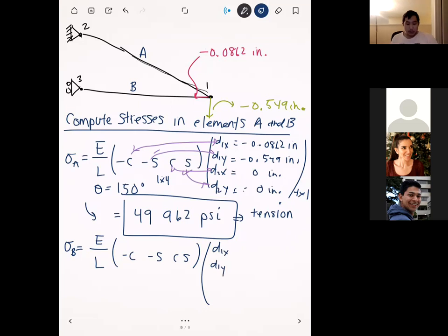And so for element B here, since this is bordering nodes 1 and 3, we have to reflect that into this vector here. So instead of d1x, d1y, d2x, d2y, our second set here is going to be d3x, d3y. In this problem it doesn't really matter because they're all zeros, but for other problems, make sure you match up the right nodal displacements with the right element.